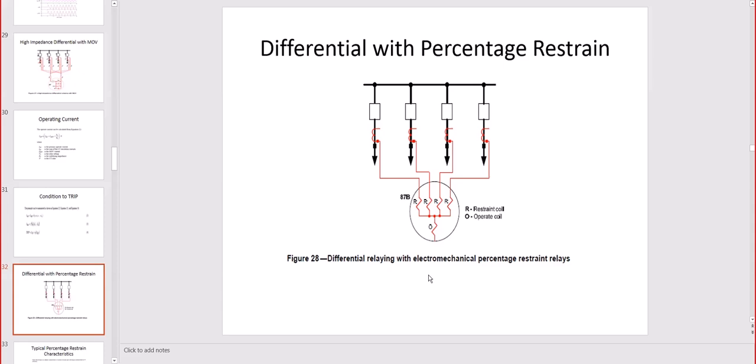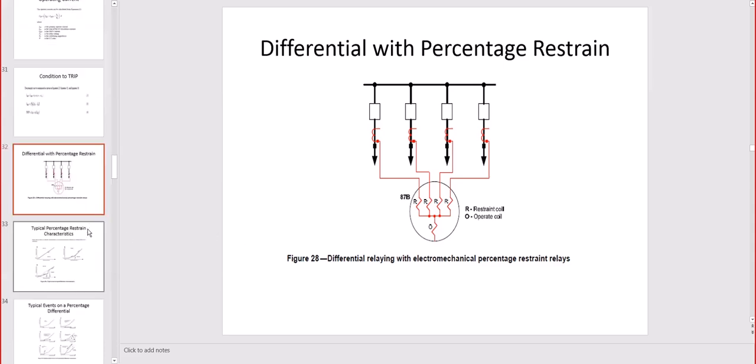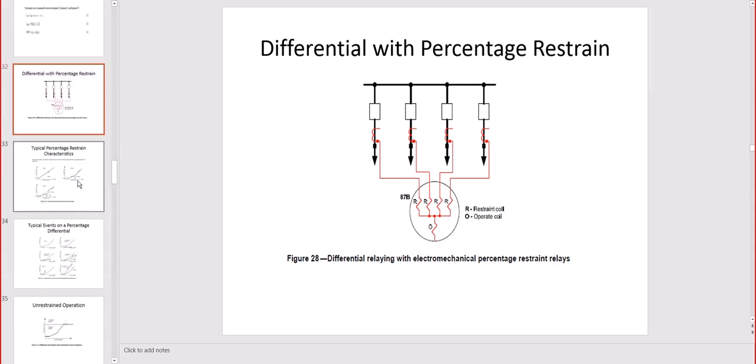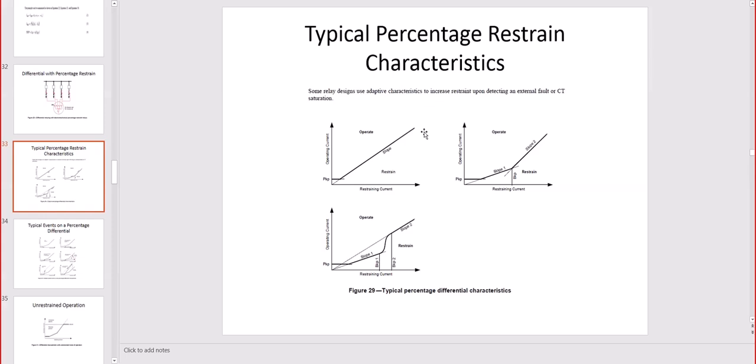So you can think about an electromagnetic disc that has a spring, and once the spring is not strong enough, the currents will induce voltage current, and the torque will be higher, so it will close the contact and will trip. That's why you have settings. You adjust actually the spring, how strong it is.